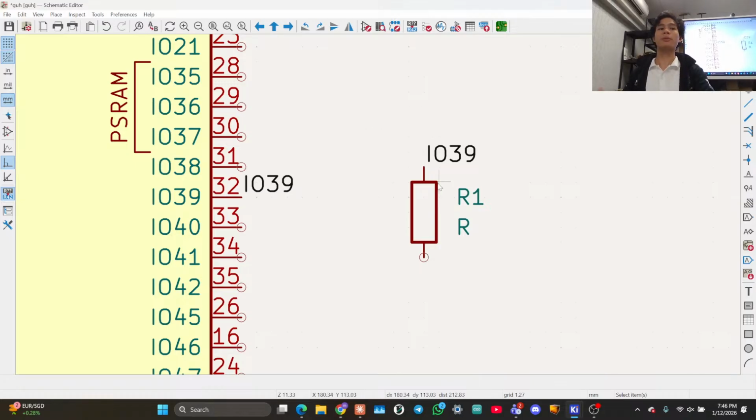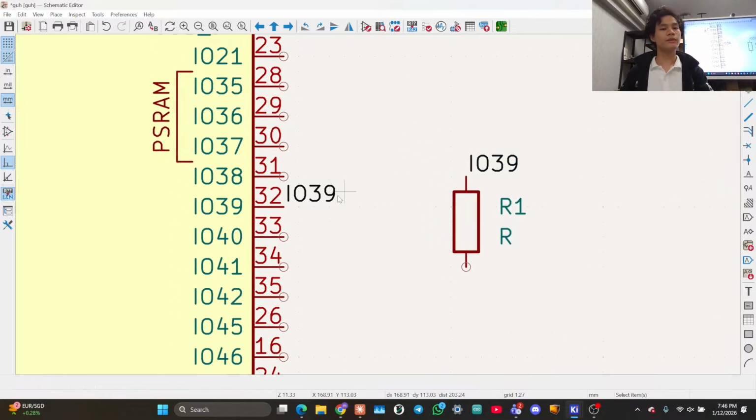And this makes complicated schematics much more readable. So this point is connected to this point. That's it. That's what net labels do. Yes, it's very convenient. If you want to do this for other things, just have a differently named net label, and then the net will be labeled something else.